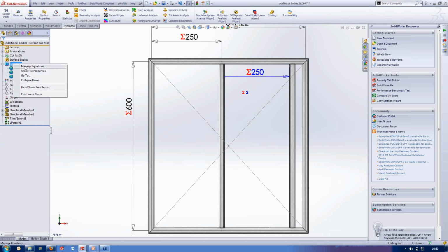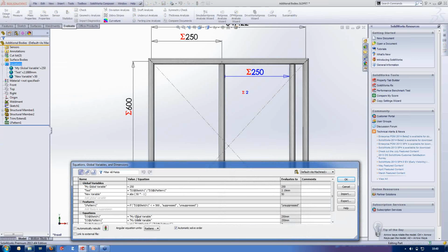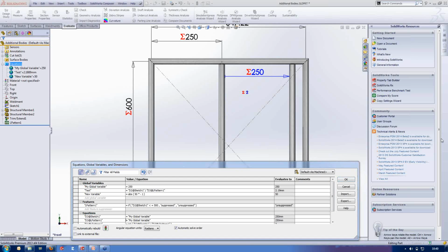You can always type the name in. So I've been pretty lazy in some of these. If I take this one as an example, I've been pretty lazy and I do like shortcuts. So I've been clicking on stuff to select it. And you can click on anything in the left-hand column to select it to pop into the right. But you can always type it in. Of course, this does involve you spelling things correctly, something which I have to confess I often have a problem with. But as long as you can see the instance count, you should be able to click on it. If you are struggling, D1 at linear pattern name should sort you out. Right, next person.